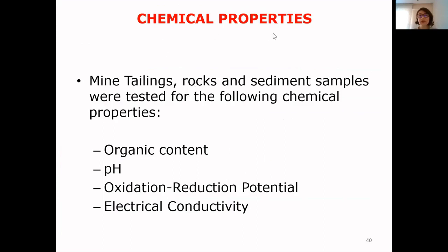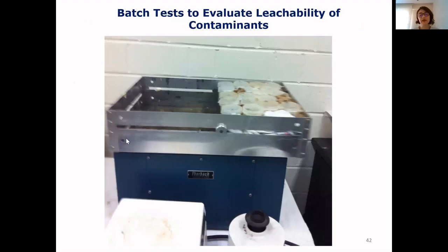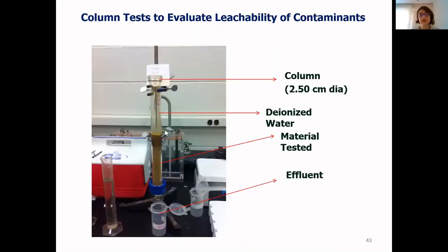We determined the chemical properties. For this, we defined organic content, pH, ORP, and electrical conductivity. To understand the leachability and bioavailability, we performed the batch and column tests. For the column test, we used a small column and DI water.